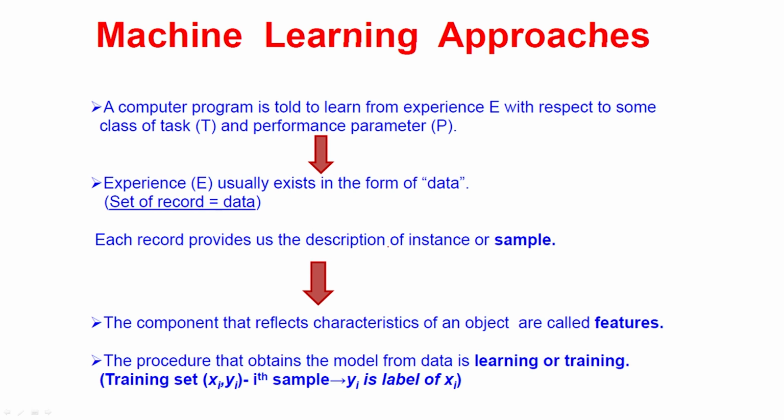Let us talk about this relationship. I talk about yield strength is equal to K epsilon to the power n. So, here we have a relationship between sigma f and epsilon, but there are 2 important parameters K and n that determine the relationship. So, the features are what? Features are K, n and epsilon for sigma f. These are the 3 parameters on which sigma f depends. These 3 important parameters. Remember, we are not talking about temperature, that can also be one.